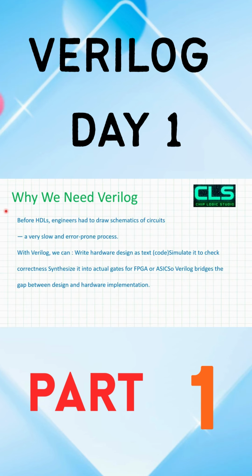So why do we need Verilog? As I said earlier, before HDLs, engineers had to draw schematics of the circuit. They had to draw a single flop, then another flop, and it was a slow, error-prone process. Our designs now have billions of transistors, not 10,000. So it is a very complex process, and nowadays it is impossible to draw a schematic without Verilog. With Verilog, we can write hardware designs as text code, simulate it to check correctness, and synthesize it